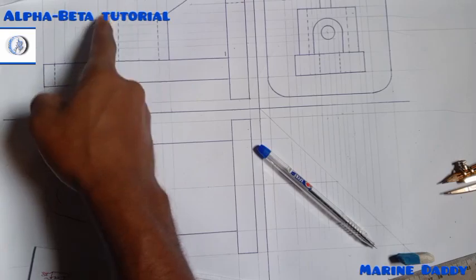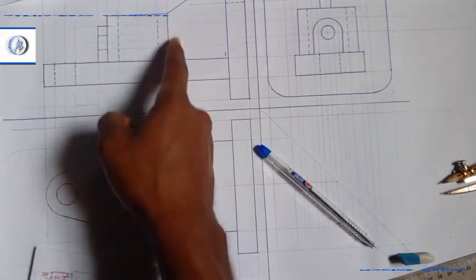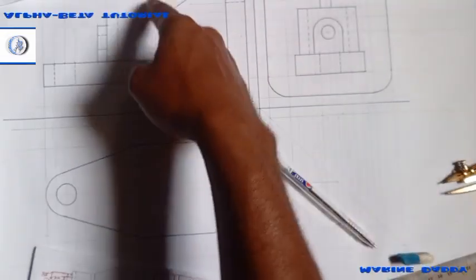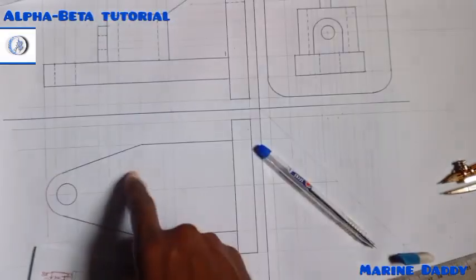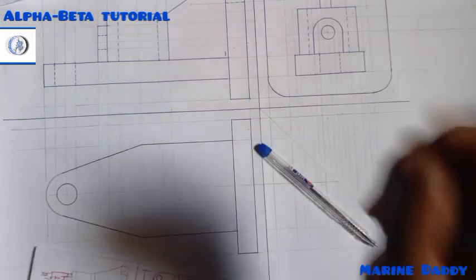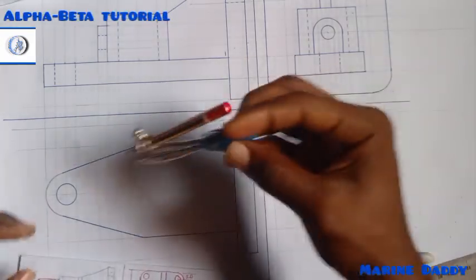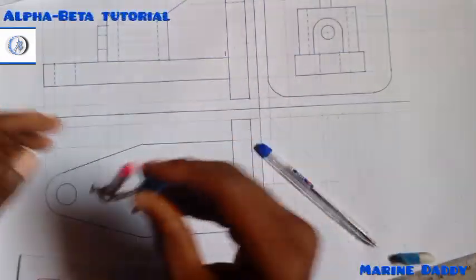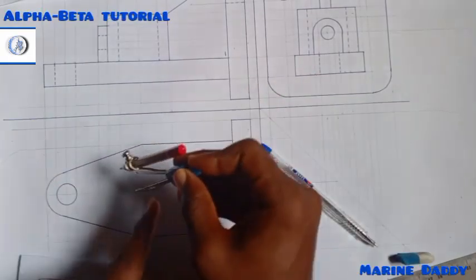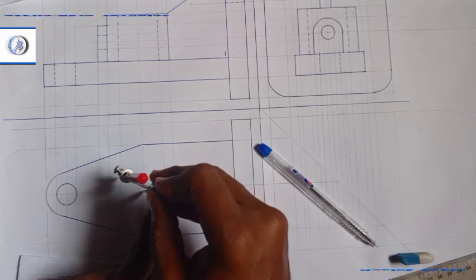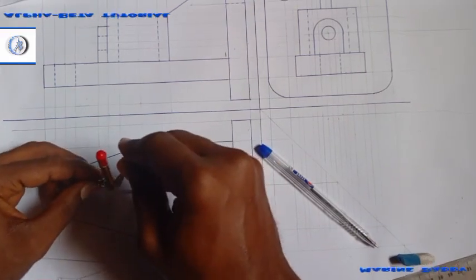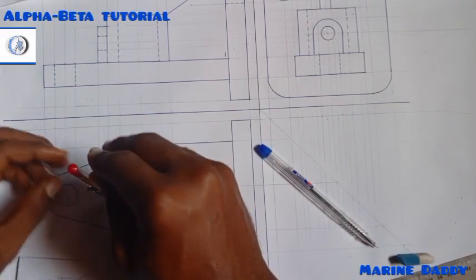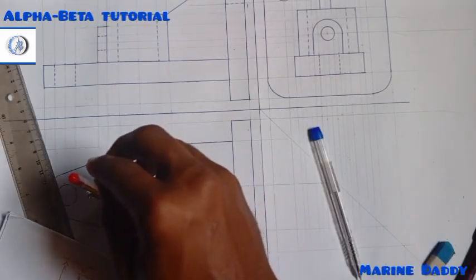So from the side we are seeing a cylinder, a rectangle, but from the top what we are seeing is actually a circle. So it's that circle we are seeing from the plan. So we need to bring out that. And they said the diameter is 60. So the radius is going to be 30 from this center. So I'm measuring 30. Put it here, then draw.